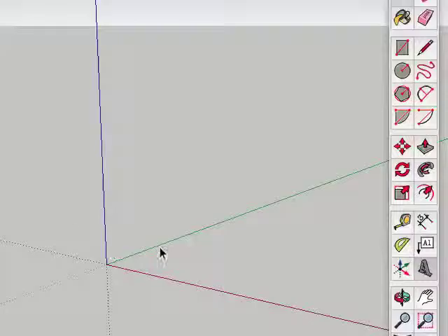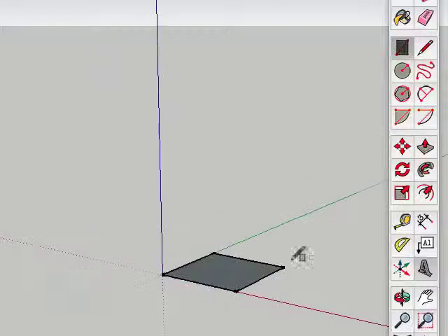So if you can go to SketchUp, I want you to get to a rectangle tool. Again, I'm going to draw out a square, and I'm using the dimensioning box down the bottom. I'm typing in 50, 50, and it'll give me a 50 by 50 millimeter square. Now remember, it's designed for houses, architects, etc. So I need to use a zoom in, or I can use a 2-finger zoom. It's up to you. What I'm going to do this time is use a push-pull tool.